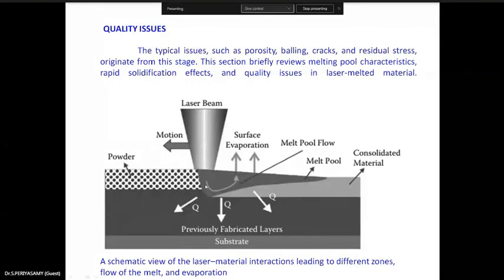The online monitoring will give an idea for repairing the cracks, pinholes or porosity, so you can watch that. Suppose the material is not melted, you can increase the specific energy striking that particular area, or move the head.